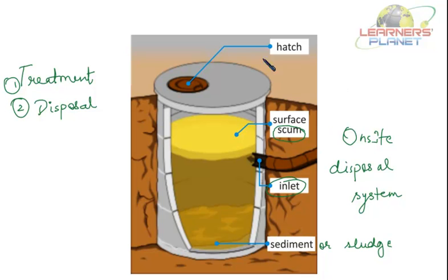Here in the figure, the brown color is the soil. Effluent from the septic tank flows down the pipes and out the perforations, and is absorbed by the surrounding soil. After that, the organic material present in the effluent is absorbed and treated by microorganisms in the soil below the distribution trenches. In this way the septic tank, which is a soil absorption system, works, and the treated water then percolates into the groundwater or evaporates.